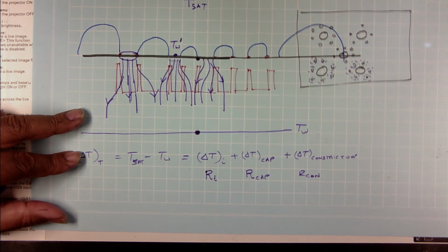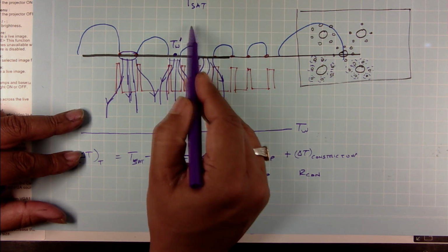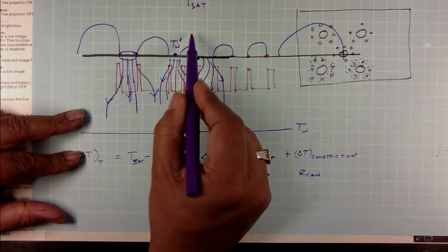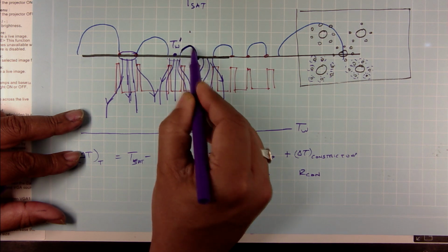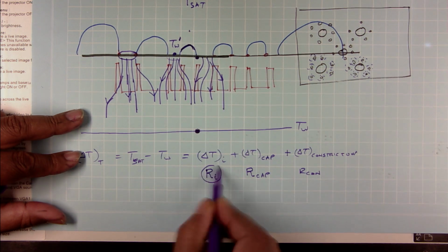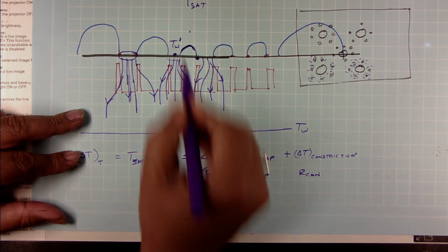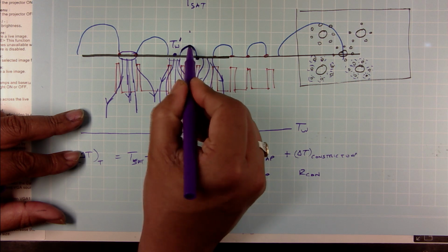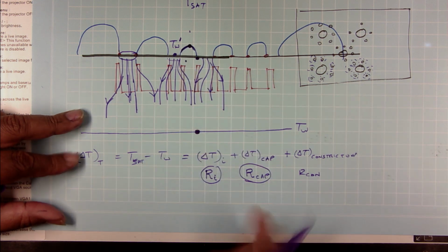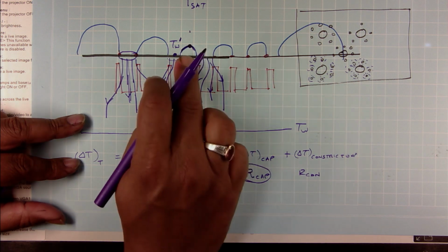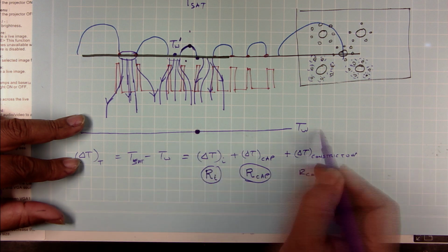So you have one resistance for this heat to travel from the pure vapor to this interface, that is your interface resistance, and then there is this other resistance which is for the heat to flow from within the bubble or within the droplet, that is your capillary resistance. And after it has crossed the droplet, it still has to go a certain distance before it hits T wall.